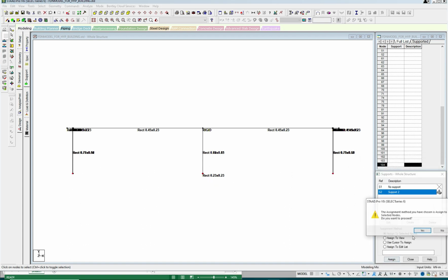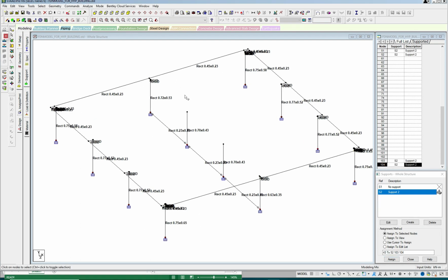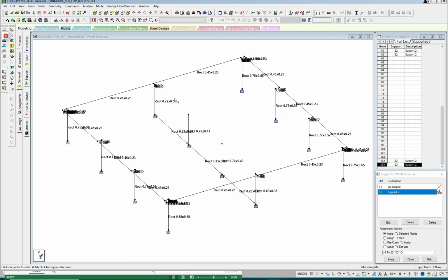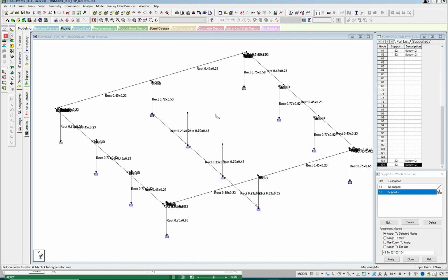Footings are fixed in 99% of cases unless it is a very soft soil. Footing cannot behave as a hinge, although it might behave as a partially fixed footing, but for design purposes we can take footing as fixed as long as the permissible pressure is not exceeded and the load does not create settlement greater than the allowable settlement in the foundation design.